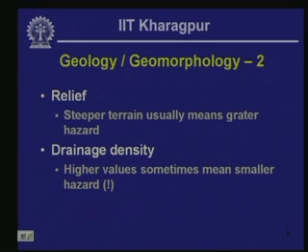Of course, I should have a rejoinder here at this particular point, because steeper terrain could also mean that the soil or rock unit underlying that particular slope is stronger and more resistant to weathering, and that in some cases could mean that you are going to have less frequent landslides in steeper terrain, because steeper terrain itself could be an artifact of strong or sound rock or soil mass.